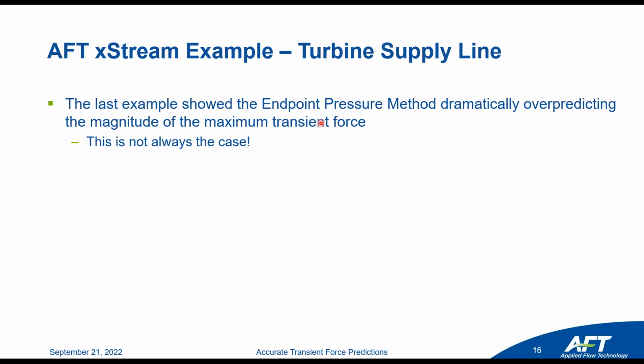What we're saying is you have a large diameter pipe with steam, and it doesn't have to be traveling that fast, but you have a lot of flow and just a lot of mass due to the diameter. And if you halt that steam turbine or whatever that end device is, perhaps by closing off the flow with the valve, just like with liquid flow, you're going to generate a wave that travels upstream.